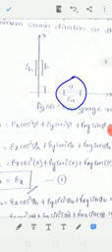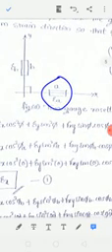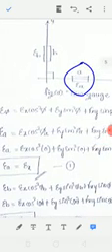In that, can I write epsilon A equals epsilon x cos square phi A plus epsilon y sin square phi A plus gamma xy sin phi A cos phi A, because we are interested in that gauge A's particular direction, right? Now wherever A is there, phi A is the angle, which I have already written here. If you look at that, the phi A angle is 0 degrees.